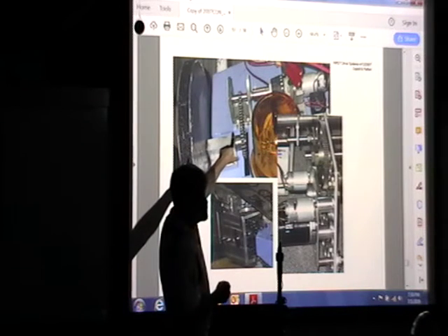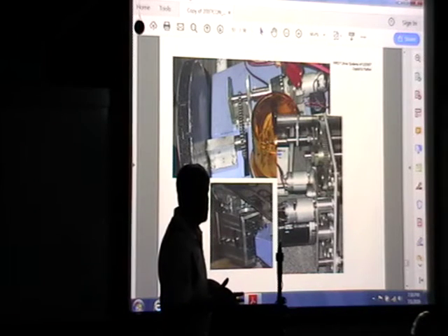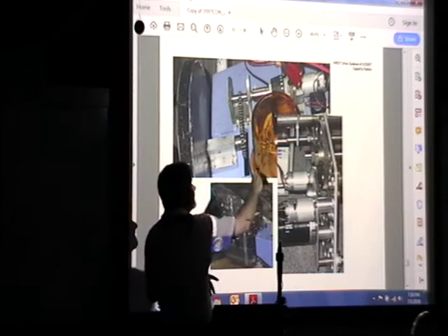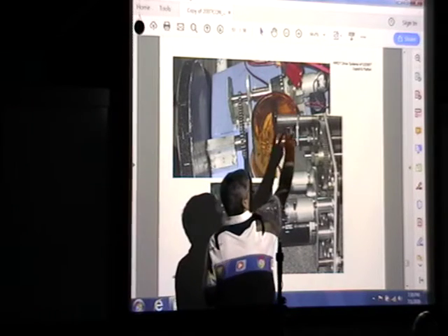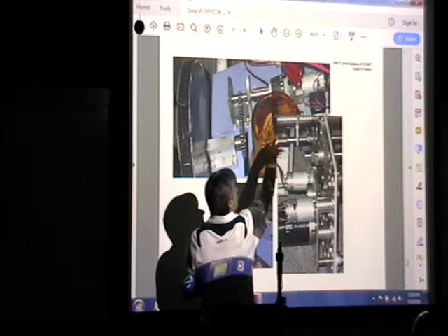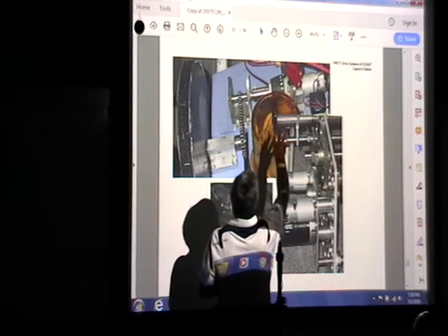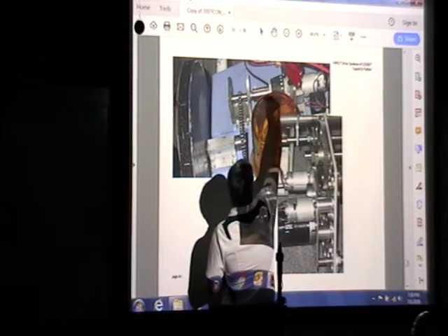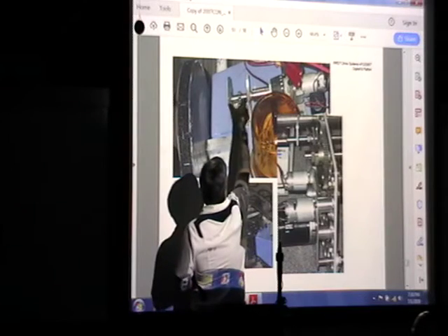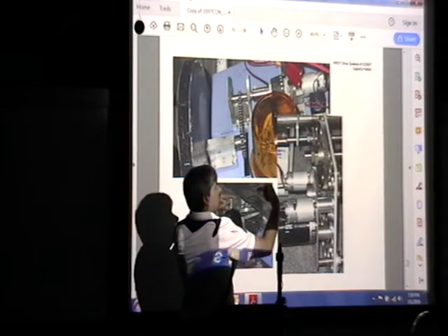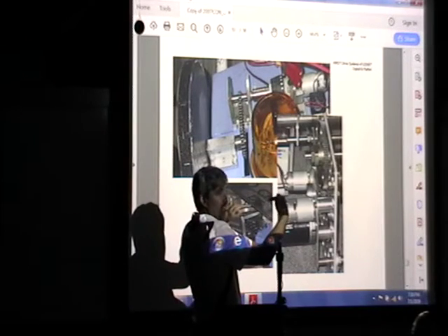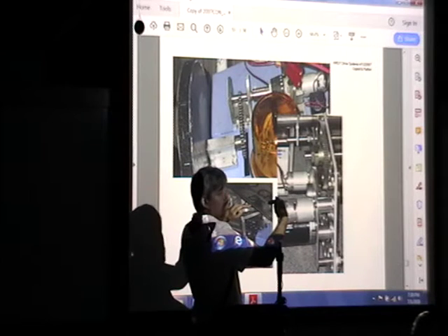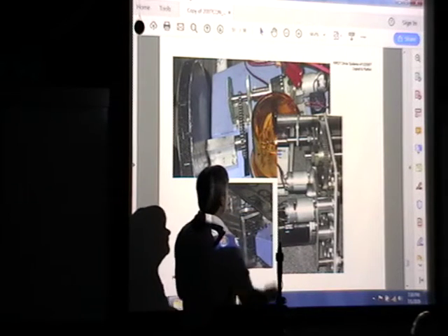That would be a perfect place to use one of those flexible couplings that I talked about, because you've got the motor fixed on one end, and the motor has two bearings in it. In this case, it looks like a reducer or a drill motor. But anyway, this is on its own rotation shaft, and this is on its own rotation shaft. You'll never get those directly in alignment, or very rarely anyway, so you put a flexible coupling in between.